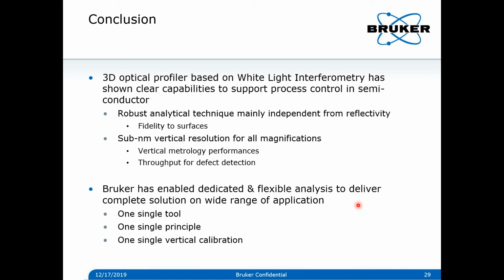And it brings back fidelity of surfaces. It brings back as well the proper vertical metrology performances aligned with respect to the specification and requirement for the processes, especially at large, low magnifications gaining sub-nanometer vertical resolution.